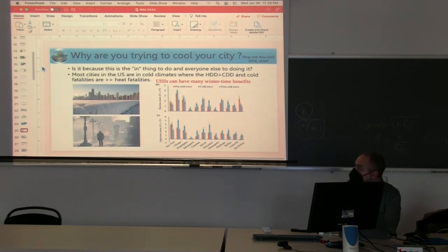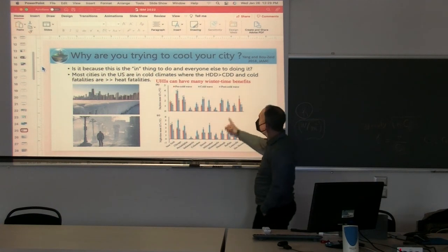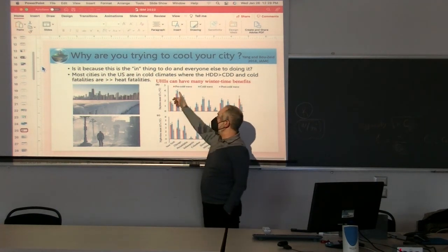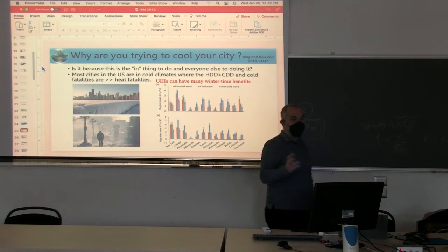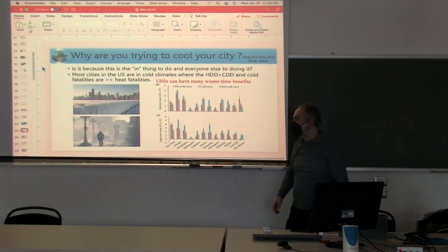But the built environment, for example, in these cases where the temperature is sub-zero, this plot shows that the cities were 4 degrees warmer than the rural areas. That's very nice, right? That saves you energy, that makes it more comfortable. So they have some wintertime benefits. In the summer, it's not the case. So some of the solutions that Anna Laura and I have been working on, the paper of Claudia, are trying to look for methods to let the heat island be strong in the winter but not in the summer. So things that are adaptable by season and climate.